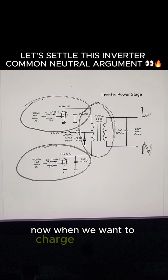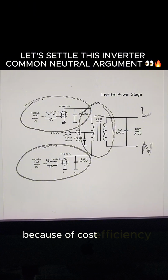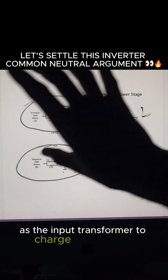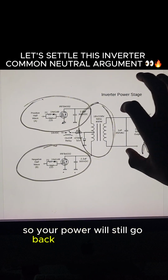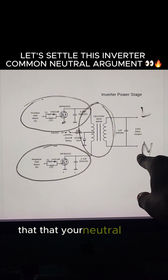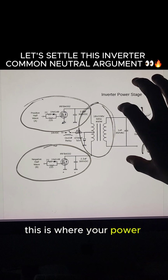Now, when we want to charge our inverter, we are now putting power back on the inverter. Because of cost efficiency, this transformer will still be used as the input transformer to charge the batteries, not a different transformer. So your power will still go back into this terminal. What does that show you? That your neutral is also still coming back here. This is where your power leaves. This is where your power comes back in.